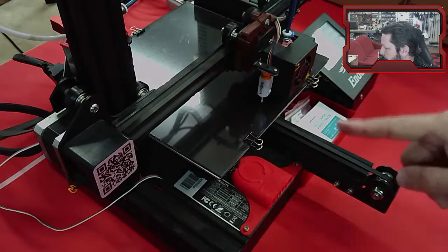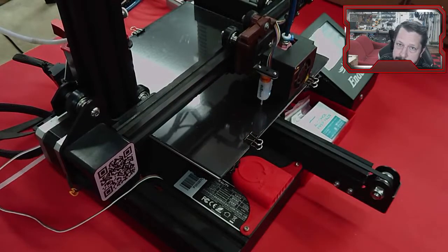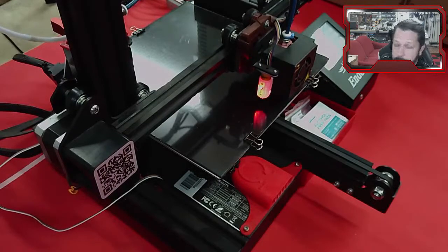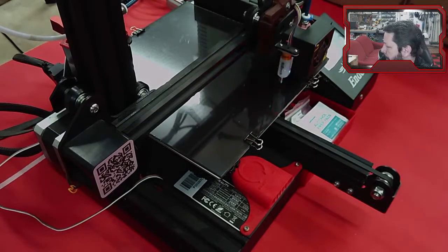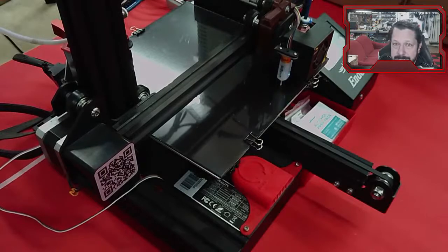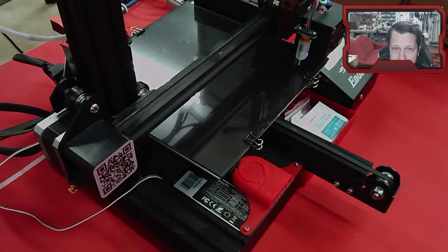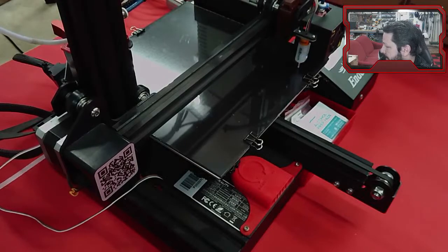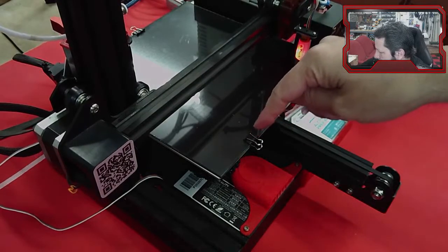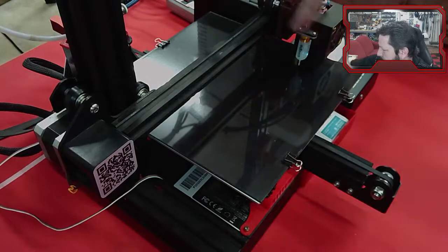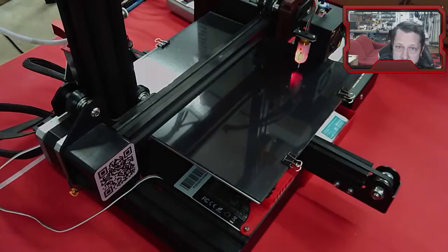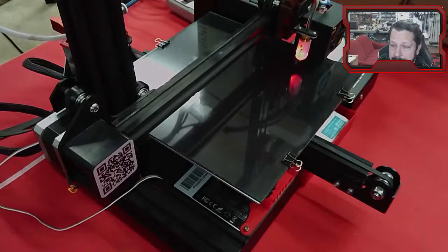But it's probing, and what it's doing is creating this map of the bed based on wherever it touches the bed. That way, if the bed has high spots or low spots, or if the whole thing is tilted, then as it's printing it can make the nozzle move up and down